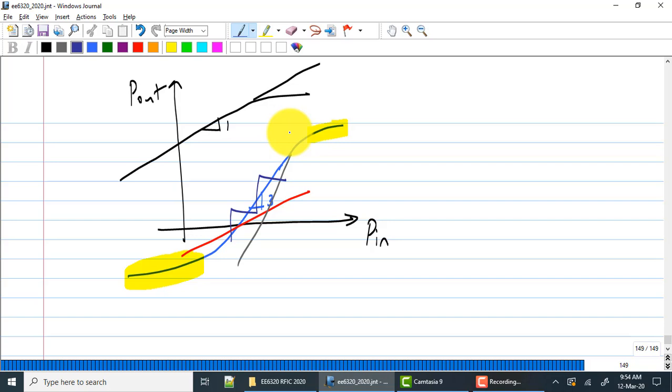I don't want to see minus 90 to 0 dBm for your curves. But what I want to see is a decent range where the LNA is expected to be used. Where is the LNA expected to be used? The typical dynamic range for a system would be maybe from sensitivity, which may be like minus 100, minus 90, to about maybe like minus 40, minus 30. That will be the input power that you would expect the LNA to be able to handle. What IIP3 spec have I given? Minus 10? Yeah. So obviously you cannot sweep all the way to minus 10.